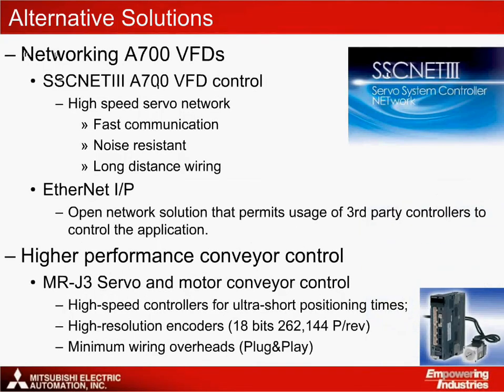The application outlined above looks explicitly at gapping control using analog control. Depending on the speed of the application and the CPU choice, network control methods may also be considered, such as SSCnet3 or Ethernet IP.